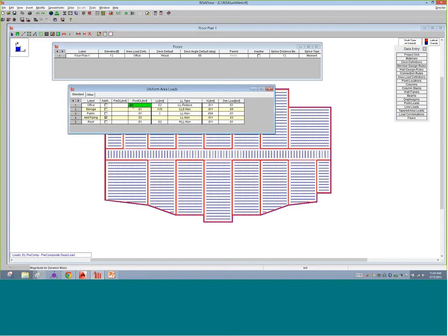So typically that's going to be just your same load as what you have for your dead load. But sometimes maybe you've added too much dynamic mass into this dead load to account for, I don't know, things that are going to be maybe office furniture, or things that might not be really part of the dynamic mass. You want to dial that dynamic load into a different number. Or maybe this is not enough. You need to add more to the mass.